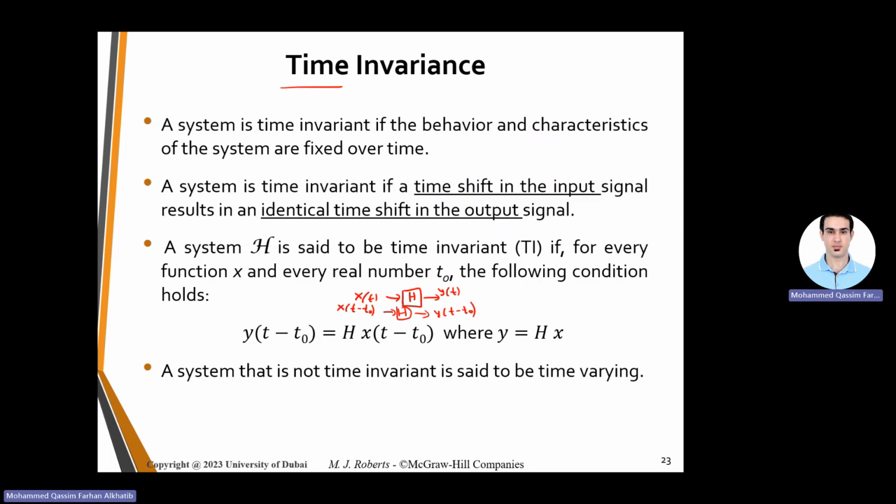All right, time invariance, which is one of the most important parts of this course, actually. To do the test for time invariance, as I mentioned, we have a delay and we have the system. Whether you do the delay first and apply it to the system, or you have the system and then apply the delay, will you get the same response? If yes, then your system is time invariant.